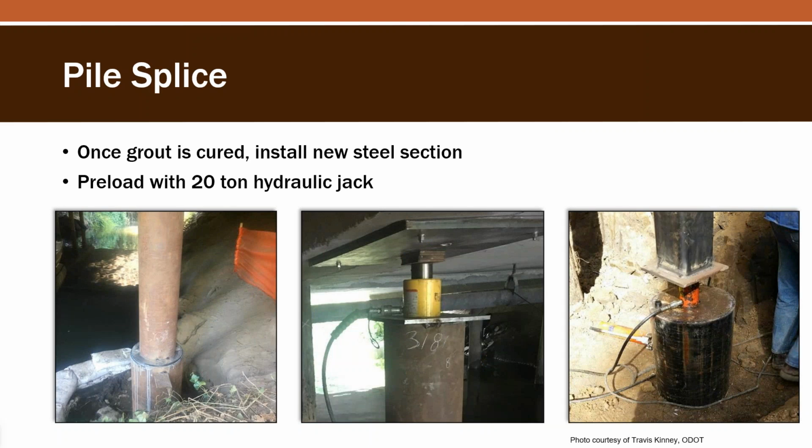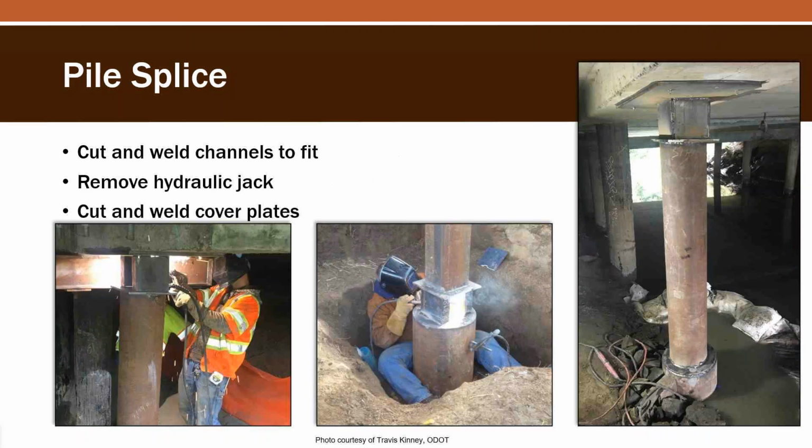One thing I would note with these is that the ones I've been involved with, we have a detail where we go ahead and reload the pile, right? During this repair process, you've taken all the load out of this pile and you want to put the weight of the bridge back into it. And so you can just use a little jack here, and with some calculations, engineers should be able to tell you, load it to 1500 PSI, and that's the weight of the bridge. You actually get that load back into where it belongs as part of that pile repair.